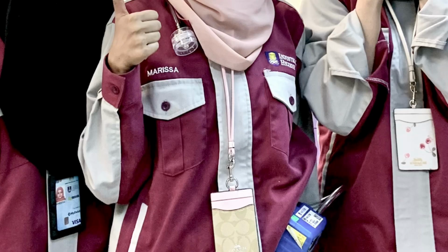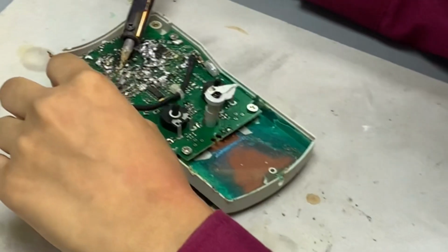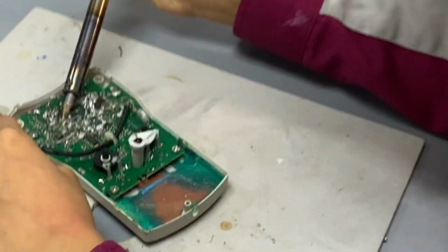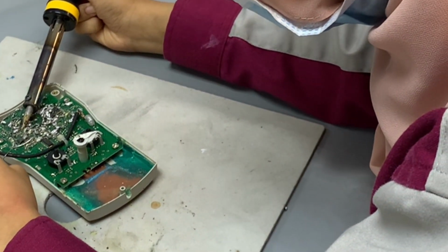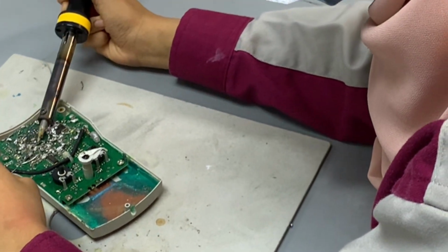During sampling, the cassette is placed at the worker's breathing zone. The inlet faces the air and the outlet is connected to the pump. The pump is switched on and air is drawn through the cassette while soldering work is being carried out. The airborne lead fumes are collected on the filter paper inside the cassette.